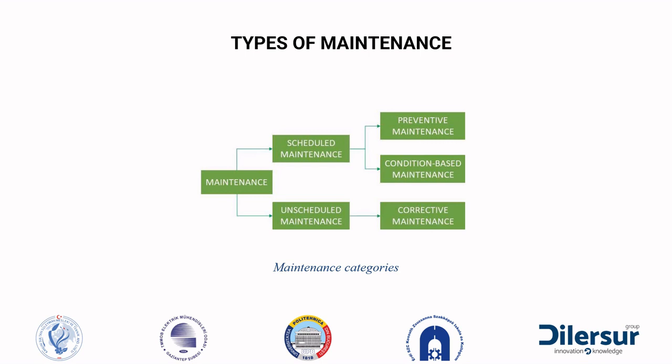1.2.2.1 Corrective maintenance. Corrective maintenance is performed when damage has occurred and involves the repair of faulty equipment. Corrective maintenance includes tightening loose connections, replacing damaged modules, replacing blown fuses, correcting inverter faults, fixing equipment damaged by intruders, substituting blown connectors, correcting SCADA faults, and remedying faults of the mounting structure.